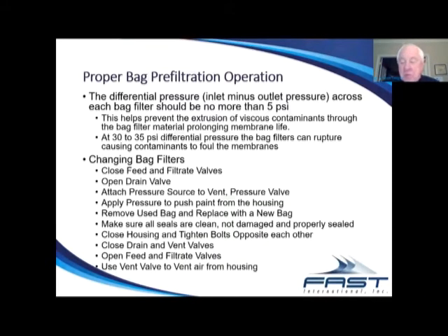Why does this help? Well, one of the things we've seen quite frequently is when we open up an ultrafiltration element and look at the bottom of the element where the feed flow comes in, you'll often see hunks or big chunks of a gelatinous material, this gooey stuff, it's like snot. It's most likely resin that has come together into a large mass. The size of it is sometimes a quarter inch or more. That should not be coming through a 50 or 25 micron bag. But because it's viscous, it can, in fact, extrude through the bags.